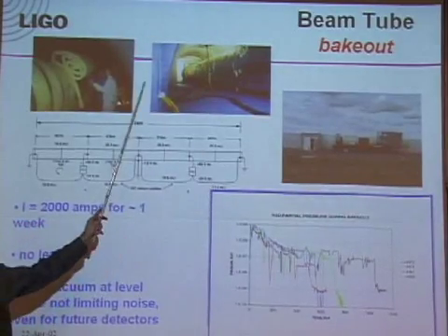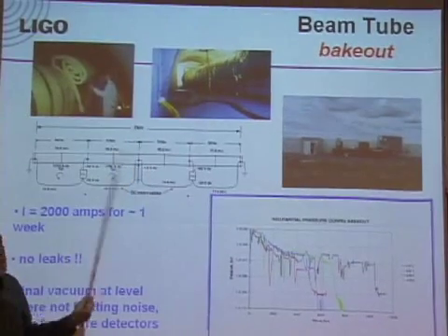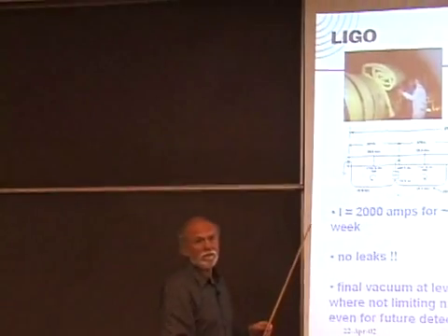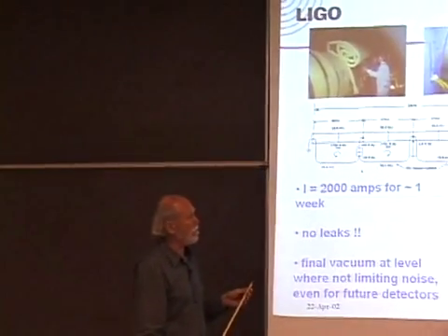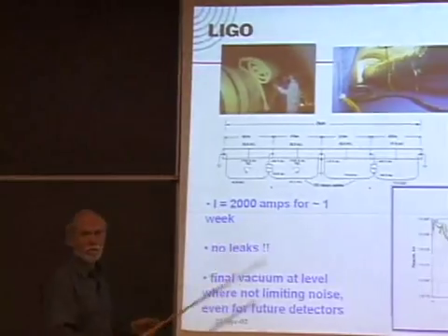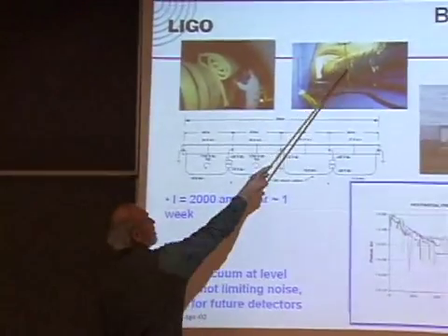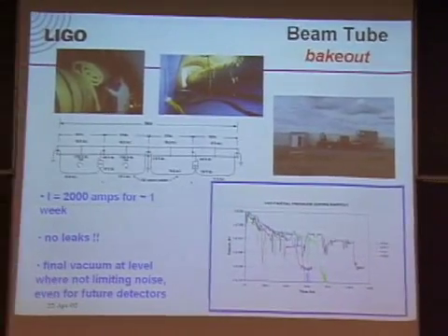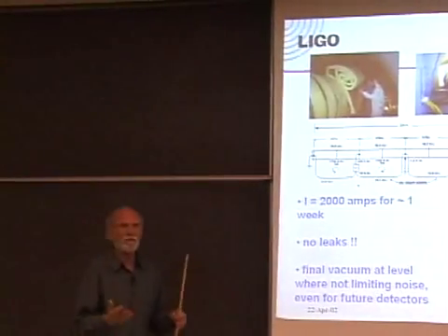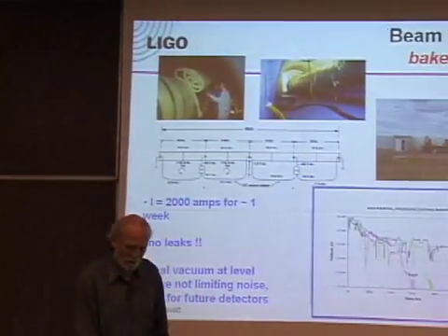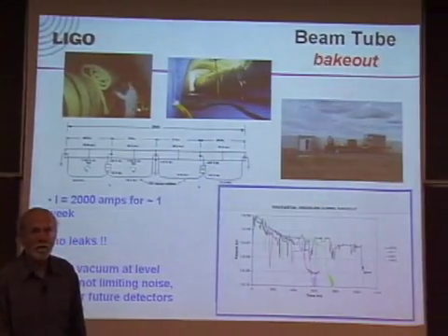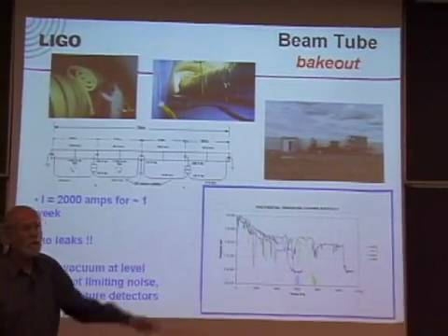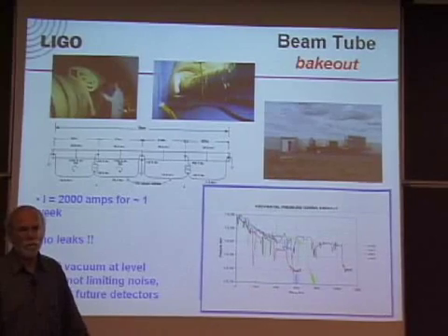This we did by borrowing magnet power supplies from Fermilab, running a current down the stainless steel, heating it up to 160 degrees C, putting house insulation around it so it's very uniform, and then letting it bake for about a week, and that's the equivalent of a century or so of just outgassing otherwise. So you accelerate the outgassing, boiling off all the... Yeah. And then at the end of it, you get to where you've improved things by 3 orders of magnitude.